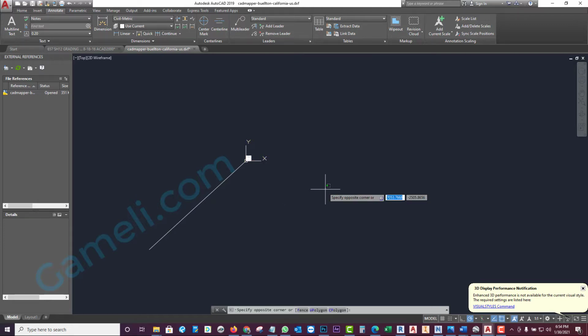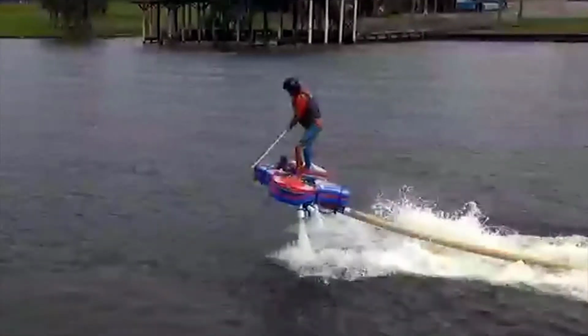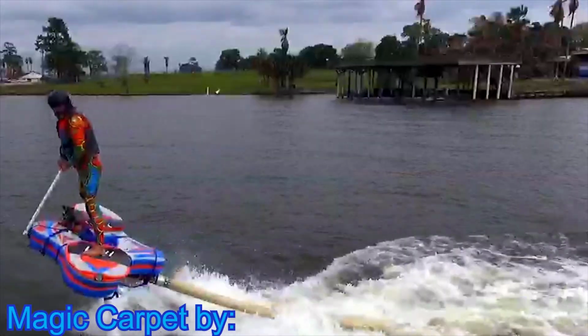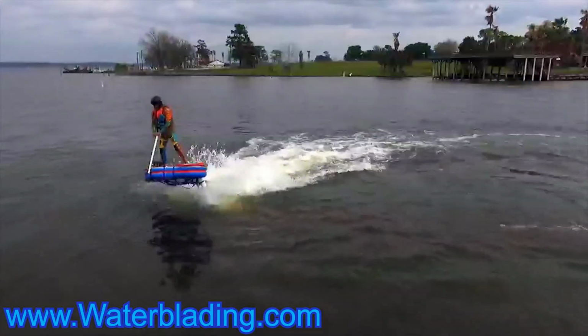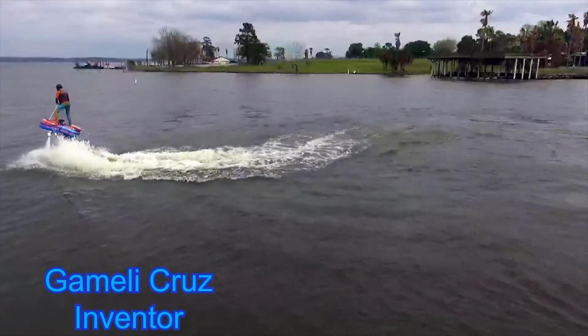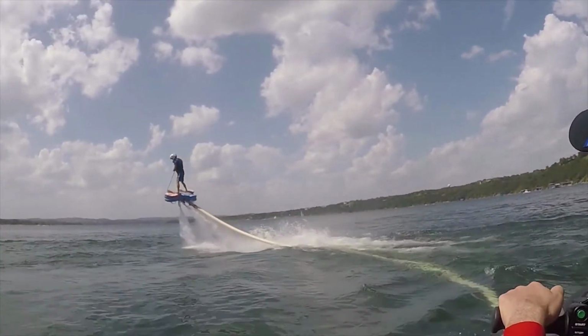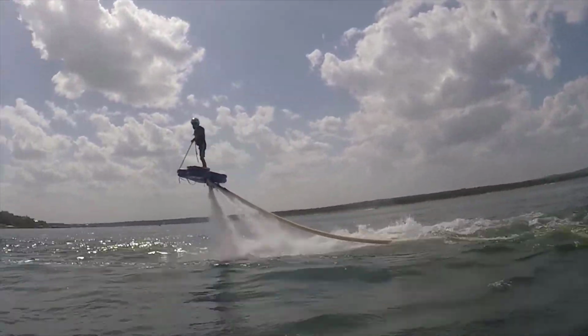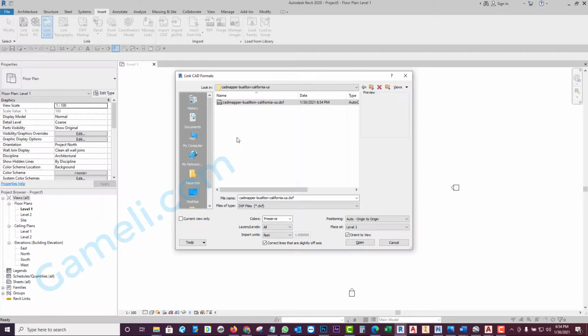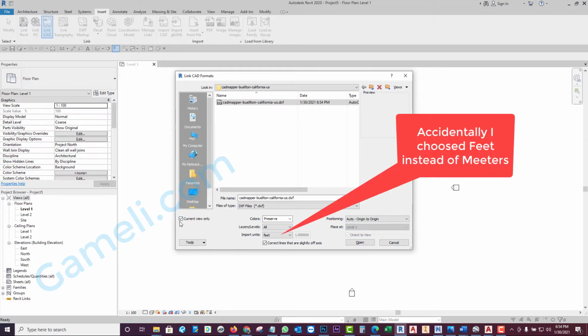Okay, so I will save this, and obviously it's going to ask me if I want to create a DWG or keep it in DXF. I'm going to keep it in DXF. I come back to Revit. I was ready to import that DXF, origin to origin, and I'm in level 1. If I want to see it in other views, I could choose here. If not, you could unselect. It will be visible only here for now.